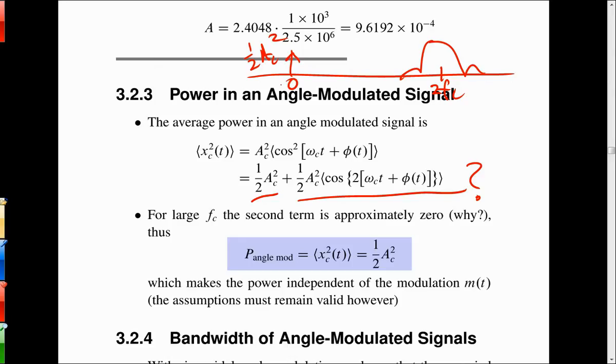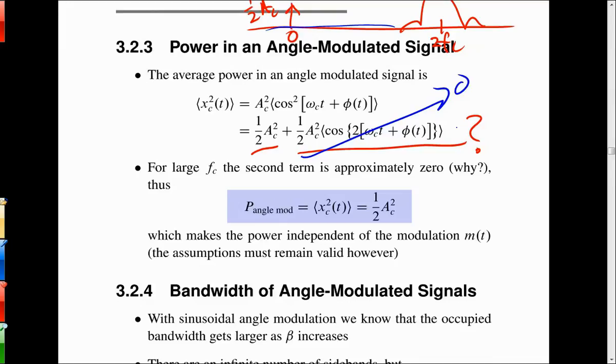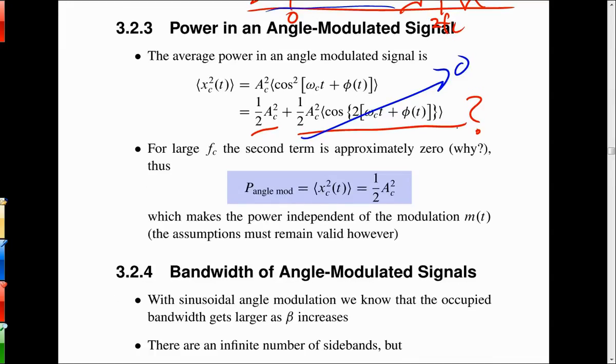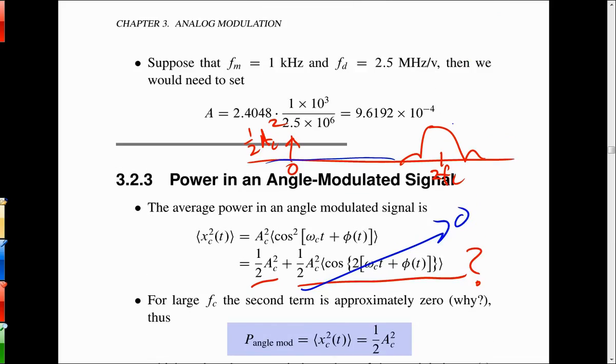If there's nothing that laps down from this signal, nothing comes down into DC, it's 0. Is that always the case, though? In a valid scenario, that's typically the way it is. Now, in the lab or in things you might do, the carrier frequency, double carrier frequency, might be low enough that it actually does have sidebands that pass through DC, and then that term is needed.